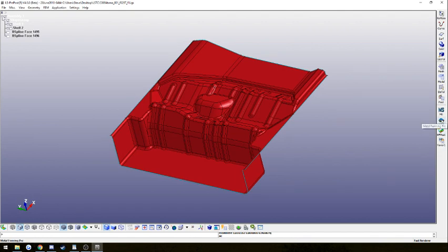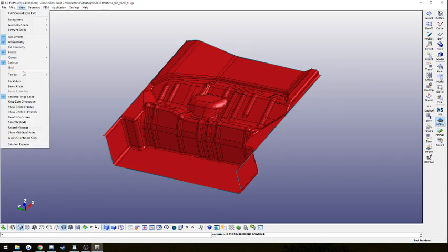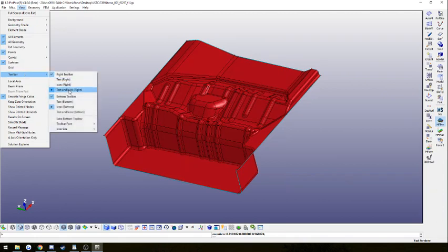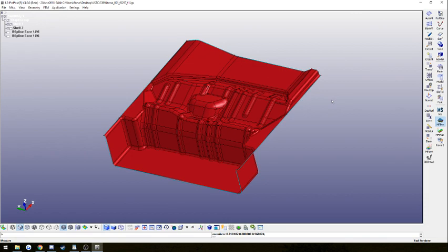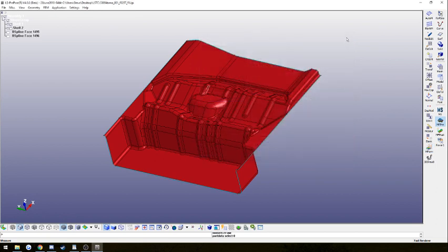Here on the right side, we're going to need to select MF Pre. If you don't have the icons or text, you can see them through View, Toolbar, Text and Icon on the right side. If you don't have MF Pre, make sure to go over the first video, or alternatively hit Control Q to open up the easy setup and just close out of it, because we're not quite ready for that yet. Anyway, to mesh the punch, we're going to go to MF Pre and hit Auto Mesh.